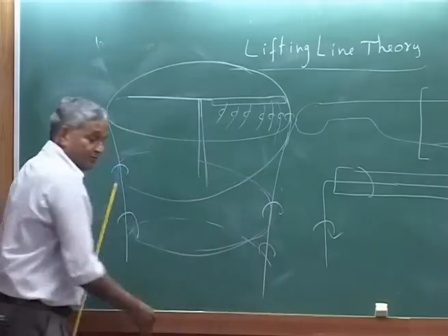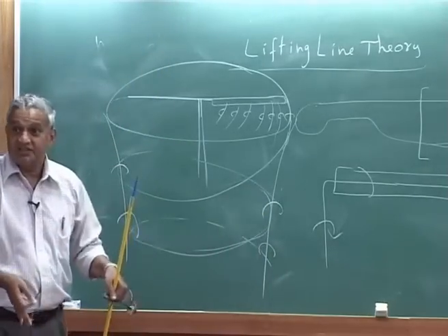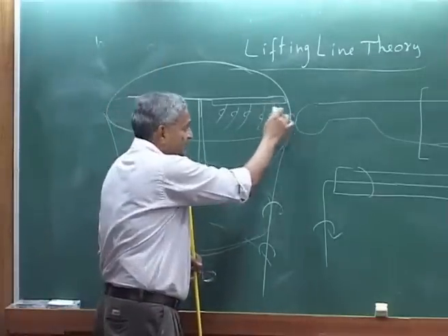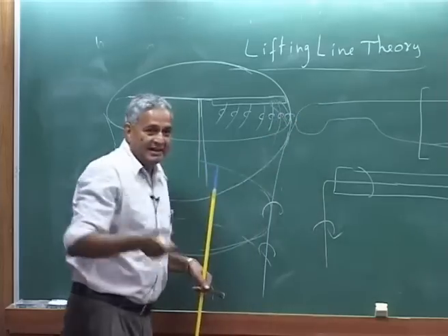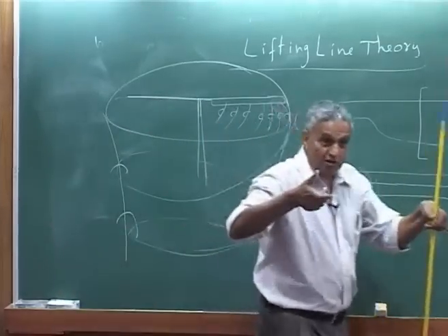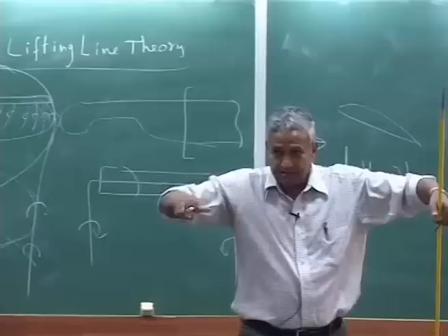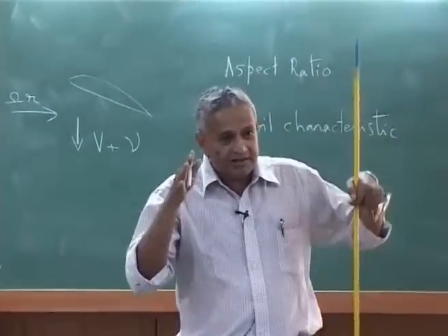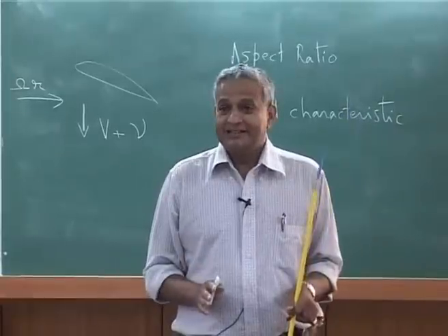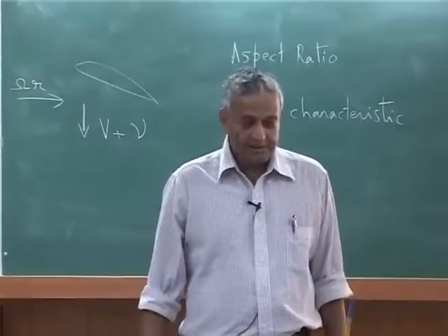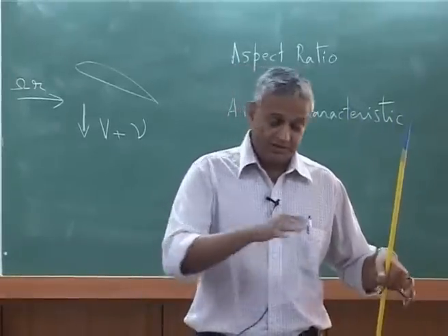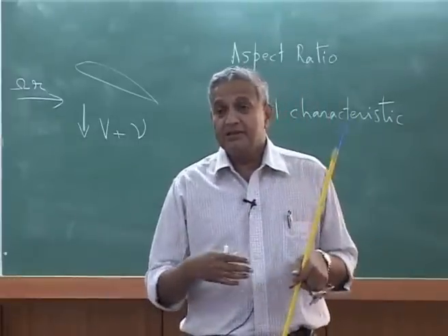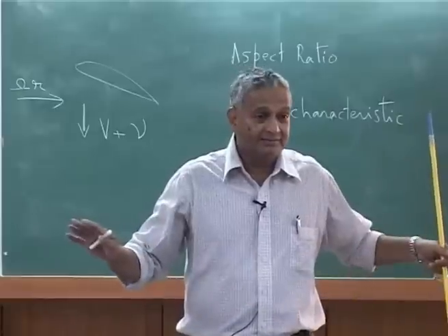So like that this will go, vortex sheet, and what will happen is initially they will start as a sheet, suddenly they will all bunch up, become a strong tip vortex, because you know that strong tip vortex and how that is convected down. That means you have to take a structure of that, that is the wake structure. Now that you have to know, or you say if you have vortex to vortex interaction, if you consider, then it is called the free wake theory.